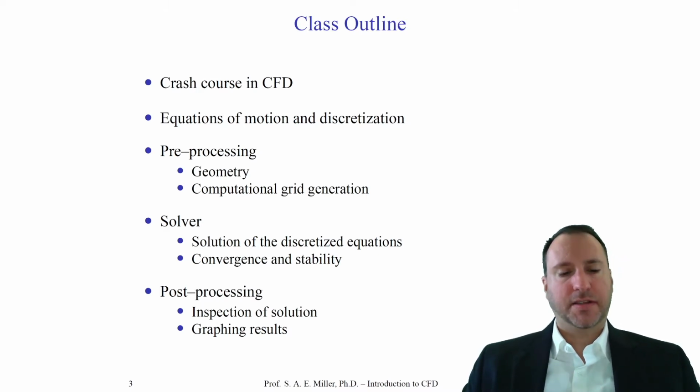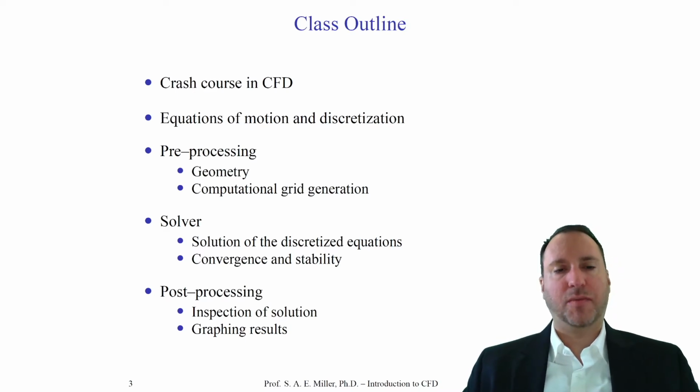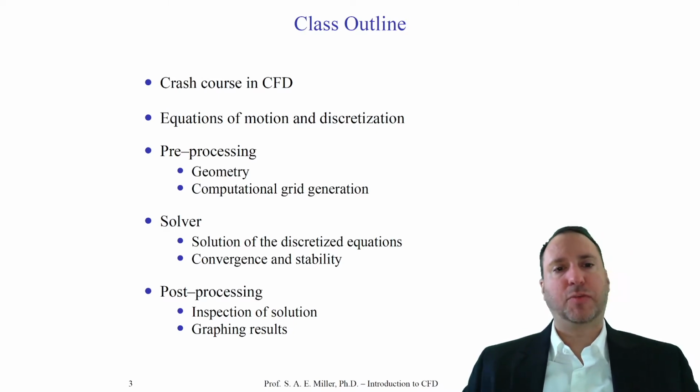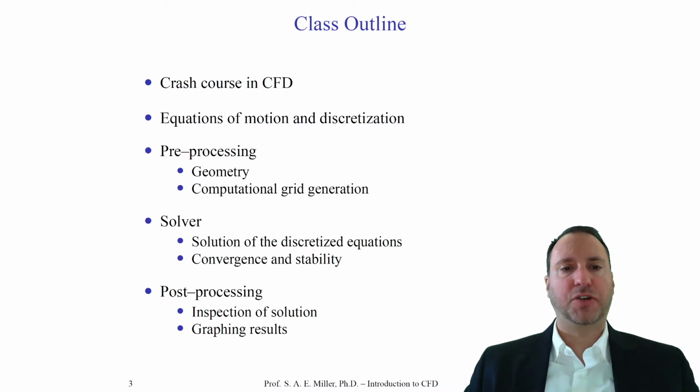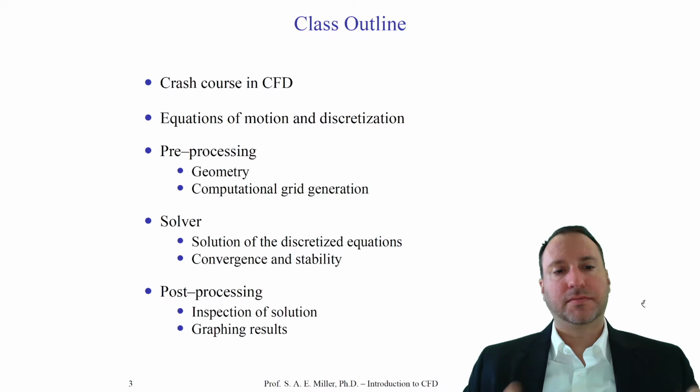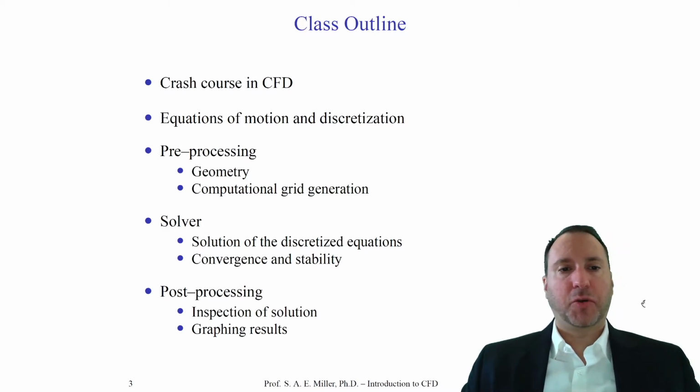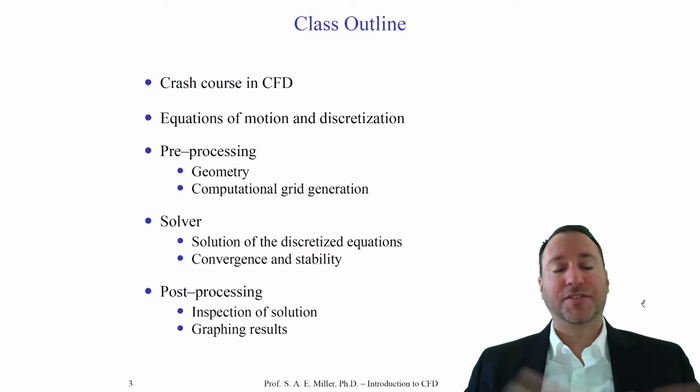Then the next step, of course, is the solver. This is where we take the discretized equations and solve the actual math problem. And this is done through linear solvers if it's a linear problem, and nonlinear solvers generally if it's a nonlinear problem. Then we'll look at two of the major important properties of the solution process, which is, of course, convergence and stability, and some other properties too. Then finally, we'll look at the post-processing phase, which a lot of students initially think is where all the fun is, and it's true, it is fun.